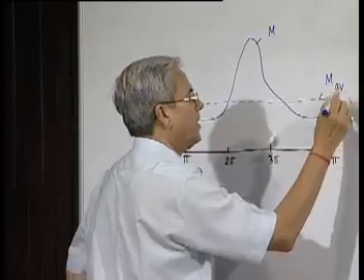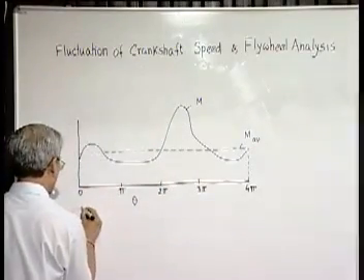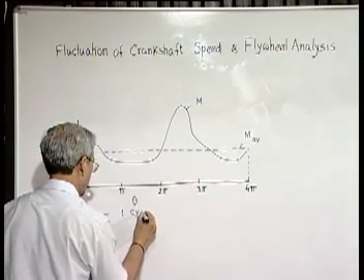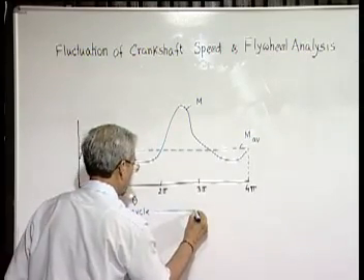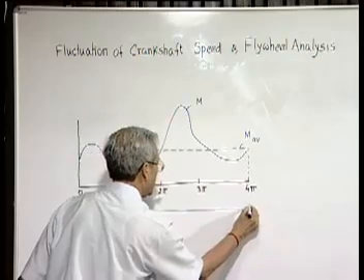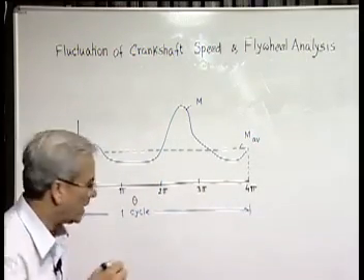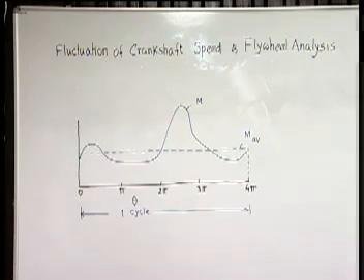How to find out? First, let us find out, this is one cycle. And in this particular case, the crank rotation to complete one cycle will be 2 rotations, that is, angle theta will go to an angle 4 pi.